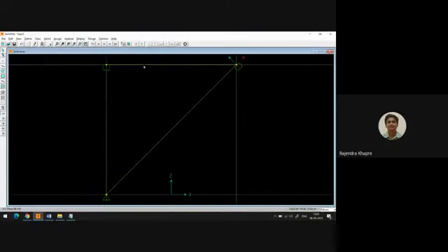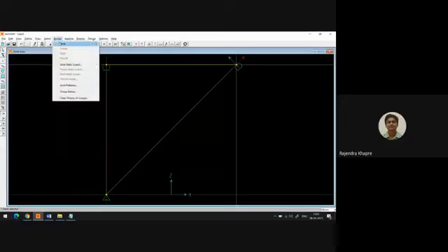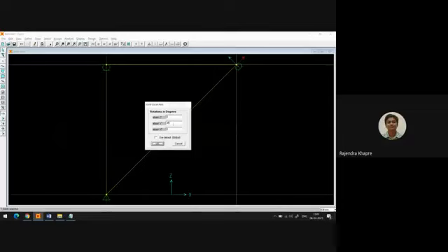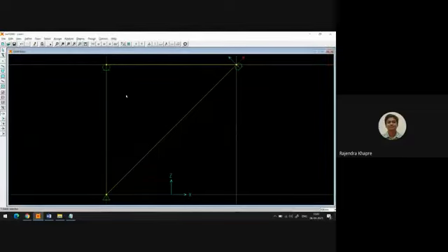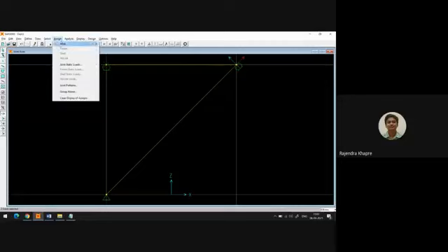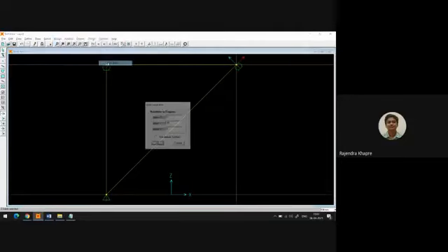Okay, all you have to do is select the joint. Okay, go to the assign joint, and here you have to go for the local axis. If you want, you can give any angle, maybe 90 degree. For example, if you want a vertical roller over here, so you can select this joint, you can go for assign joint and say local axis.